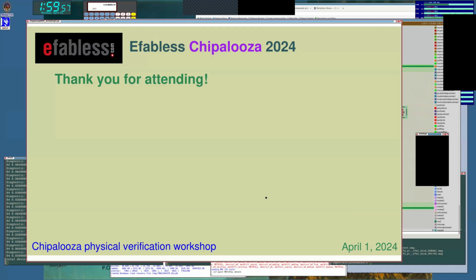Is there a limit for how large a local interconnect rectangle can be? It's from Louis Rodolfo. Sorry, a limit for? A local interconnect rectangle can be. Oh, a local interconnect rectangle. The local interconnect rules are written very strangely. What they limit is the aspect ratio. So there is no particular size limit, but they don't want it to have an aspect ratio of more than 10:1. And that is not even able to be checked in Calibre, as far as I know. So it's really just a recommendation.